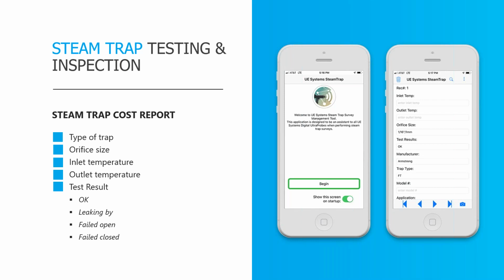So, if we're making contact on the outlet or the discharge side of that trap, when that trap cycles open and releases condensate, we're going to hear that, but then we'll also hear when it shuts back. And then a few seconds later, typically, we'll hear it cycle open, and then we'll hear it shut back. Now, your other sound characteristic comes in with your float and thermostatic traps.